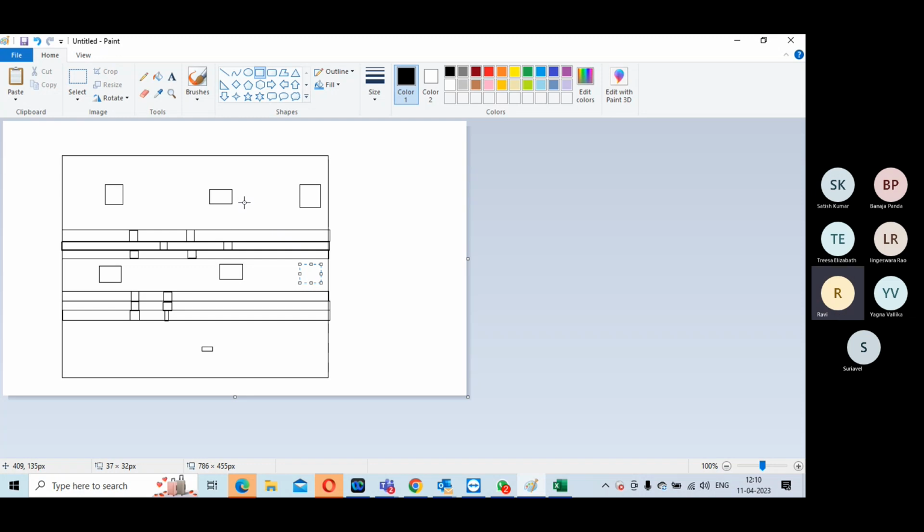For spare cells, you have to create a hard bound, but not make it exclusive. If other cells have space to sit there, they can sit without impacting the condition. Don't create an exclusive bound, create a hard bound, but allow other cells, because you won't be able to estimate exactly what the bound is. Not required to make it exclusive.